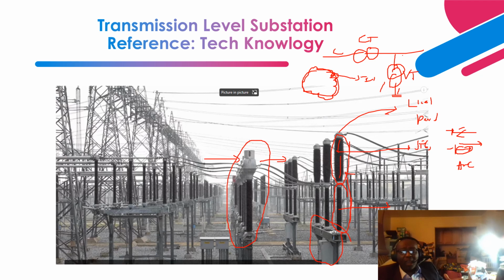And if this arc is not extinguished in a timely manner, it can form a restrike voltage. They call it transient recovery voltage. It can create another high voltage and allow a conductive element to flow, even while the circuit breaker is in open position.